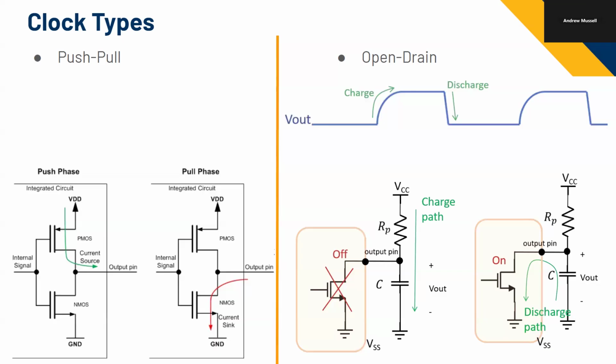That was a lot. Please ask questions. Yeah, like how does the internal signal actually drive the push-pull? Yeah, so a little bit into MOSFET device physics. This is the MOSFET here on the bottom left. And this is an NMOS, so it turns on or off based on the voltage between the gate and the source. So VGS, the voltage across here.